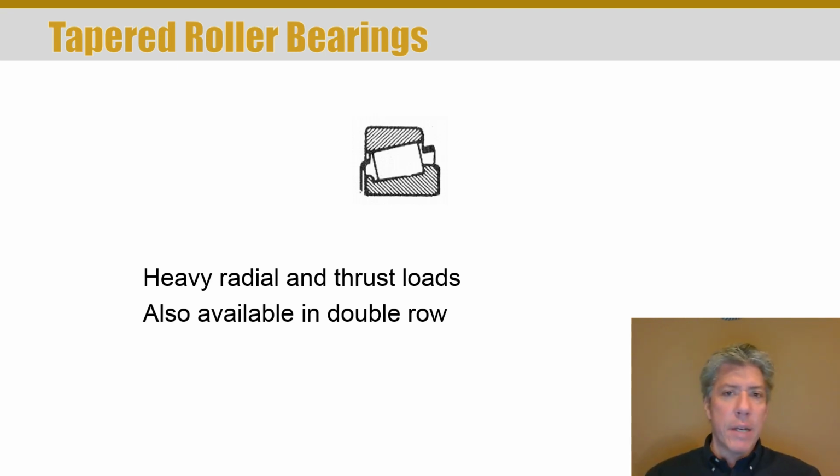And in fact, bearings are one of those areas where you really have to go to the manufacturer and ask for an applications engineer just to make sure your design is going to work, or make sure you follow their design guidelines religiously, because it turns out bearings are very standardized, and you can switch out bearings from one manufacturer to another pretty easily because the sizes are all the same. That doesn't mean you're getting the same kind of bearing.